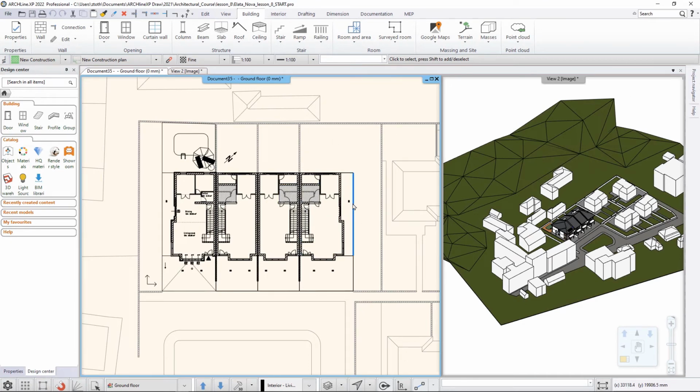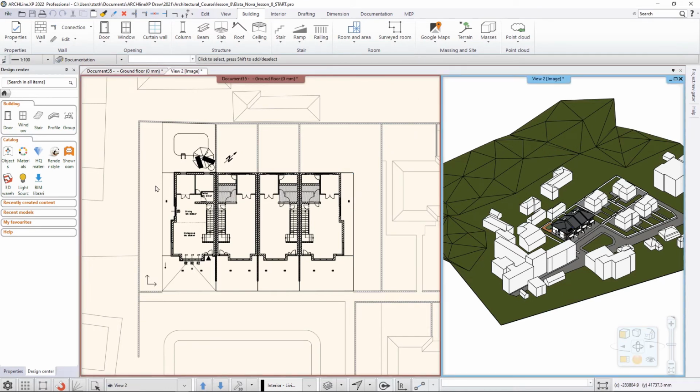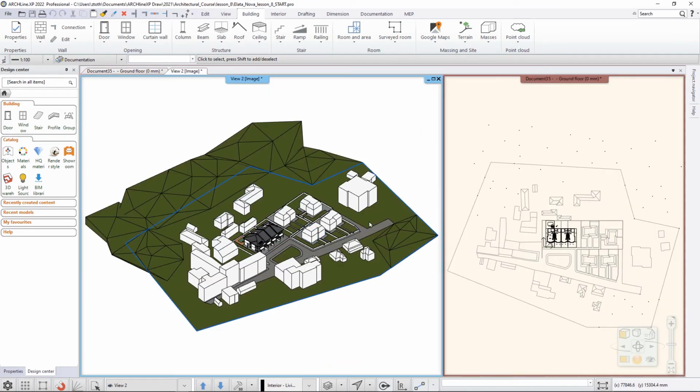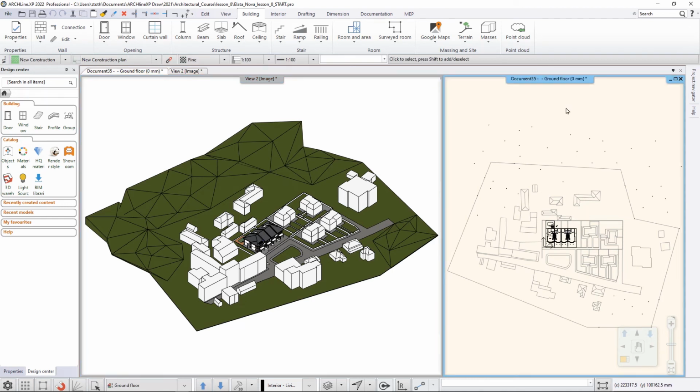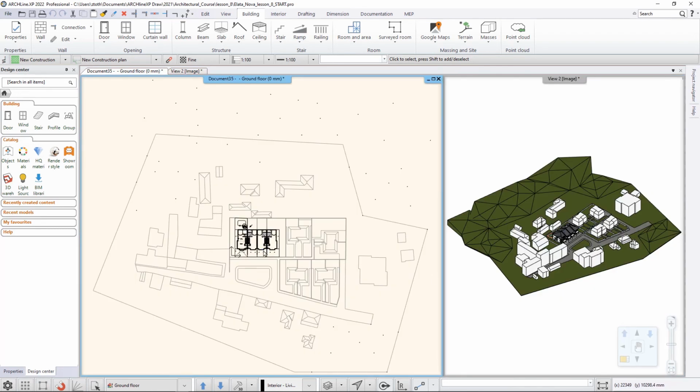You can also enlarge active content, which means if I would like to swap this drawing into this area, this is the working area, then I need to select it, move my mouse over to this area and find the magnify view or enlarge active window command. If I click on that, the software will swap the two drawings and make this at the left hand side, and all the rest of my drawings will come to the right side. To switch back, I can click on the 2D content, use this command again, and for example zoom into this content.